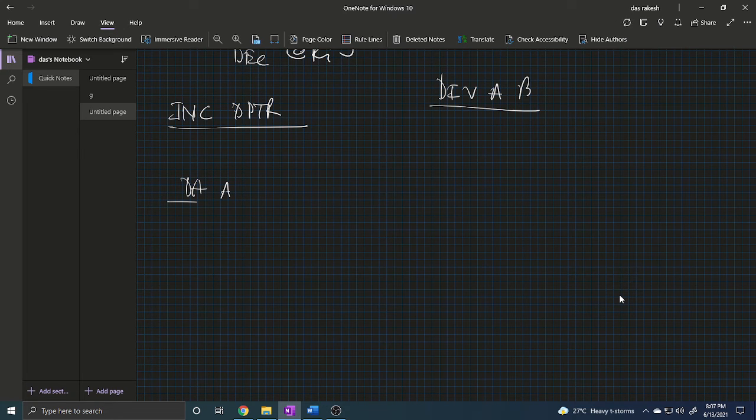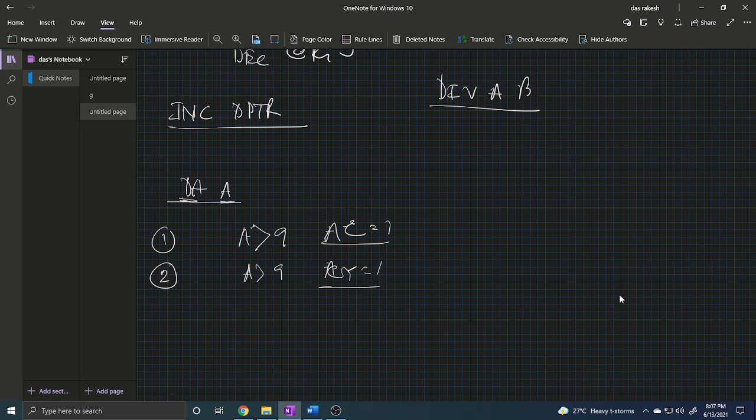The decimal adjust basically follows two rules. The instruction format is DAA, decimal adjust of accumulator, and two algorithm rules are followed. Number 1, it adds 6 to the lower 4 bits of the accumulator if they are greater than 9, or if the auxiliary carry flag equals 1. Then it adds 6 to those 4 bits. And number 2, it also adds 6 to the upper bits of the accumulator if the upper bits are also greater than 9, or the carry flag equals 1.